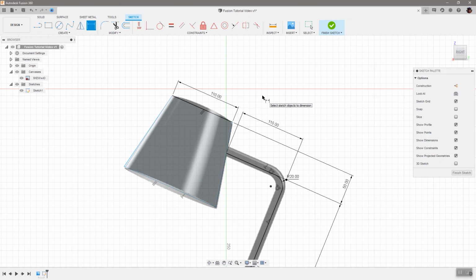Now, there is one thing I want to make sure, that the left side and the right side are symmetrical, right? They don't have to be at the moment. If I press the escape key, I could move things around and be quite wonky. I don't want to have that at all. So let's make sure that this is sort of symmetrical, and a couple things happen at once. I'd like to have a center line. So let's draw that center line. Create line. And if I move my mouse slowly along this line right here, eventually you'll see that blue triangle turn up. That is the midpoint of that line.